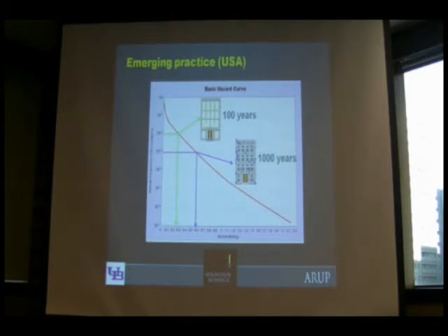Now we've actually spelled out some performance levels and some hazard levels, so we're being a lot crisper about the whole process. So one might say that a standard design might make use of the operational performance level for earthquake shaking with an annual frequency of exceedance of 1 divided by 100.